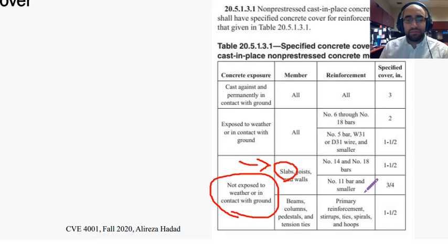For the slabs, it is very rare to reach these large bars. It might happen for the case of very wide spans or extreme loads. But for the case of regular design and regular buildings, usually the smallest bars are going to help us, or number 4 or number 5 bars will usually get the job done.